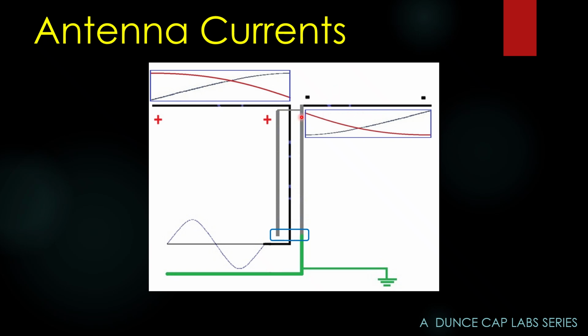For this antenna current to form, this junction here has to go negative. Technically, it can't, because the coax shield is supposed to be grounded and at ground potential. Now, at certain wavelengths of coax, that kind of varies a little bit. The way to fix this is we want this shield to stay at ground, this to swing high and low, and these two to swing together in opposite polarity like the ladder line fed dipole.